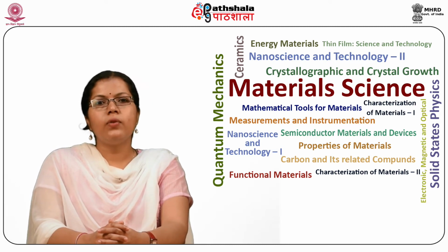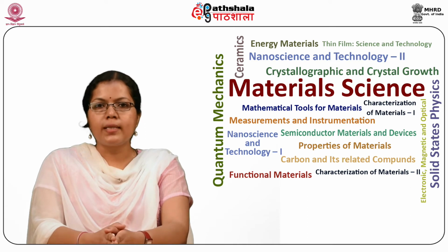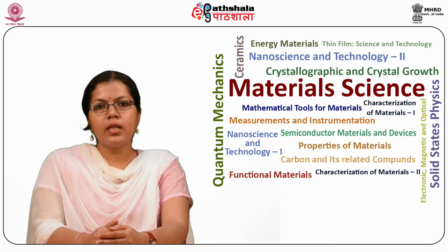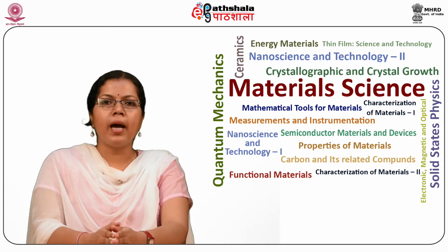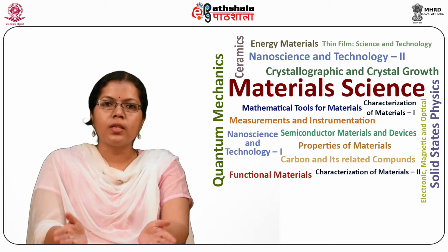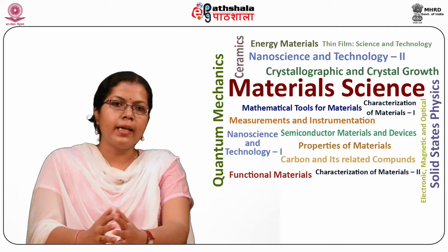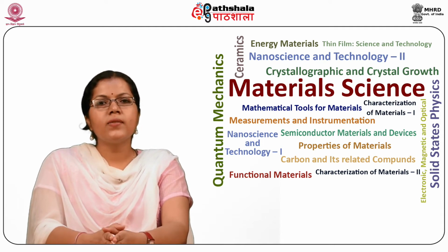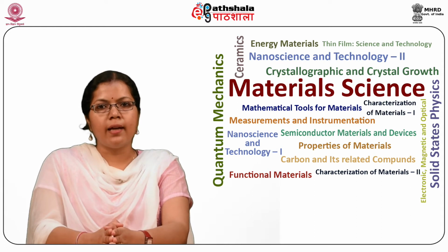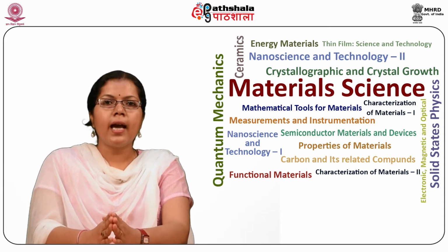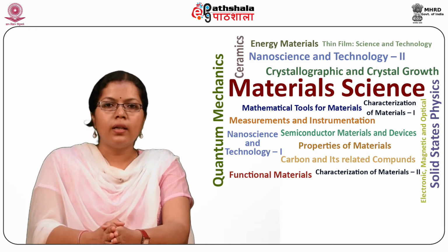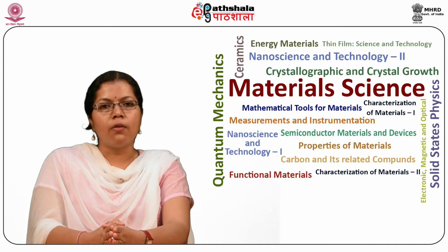These photocells were designed to overcome the low sensitivity of the vacuum-type photocell. The sensitivity of the device is improved by increasing the number of electrons produced at the cathode by a gas discharge. There is not much difference in the construction of a vacuum tube and a gas-filled photocell, except that the latter one contains an inert gas, usually argon, at low pressure of about 1 mm of mercury.